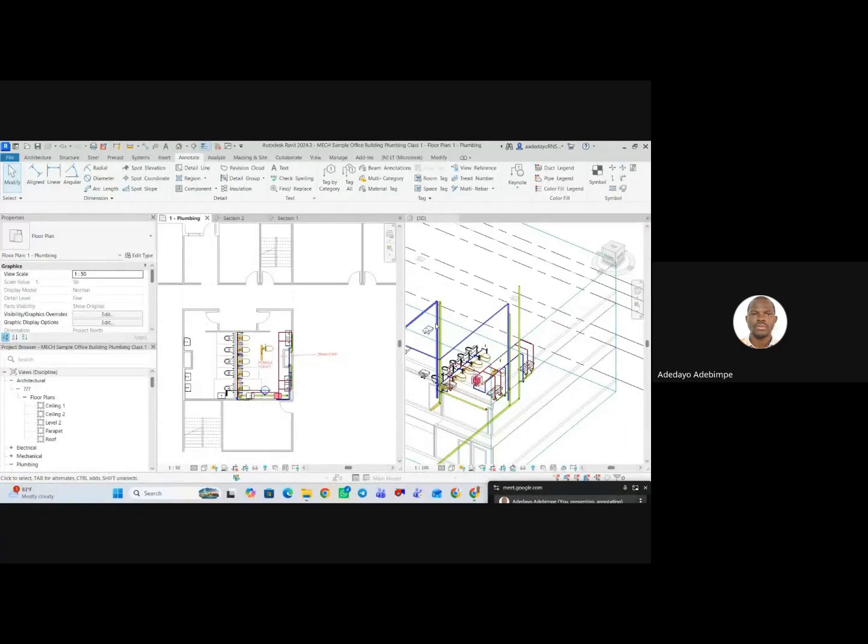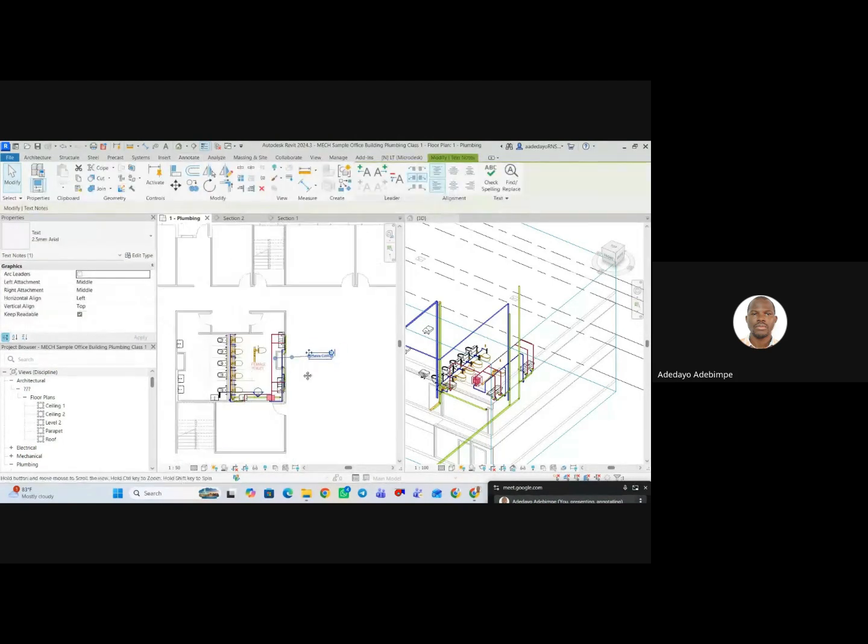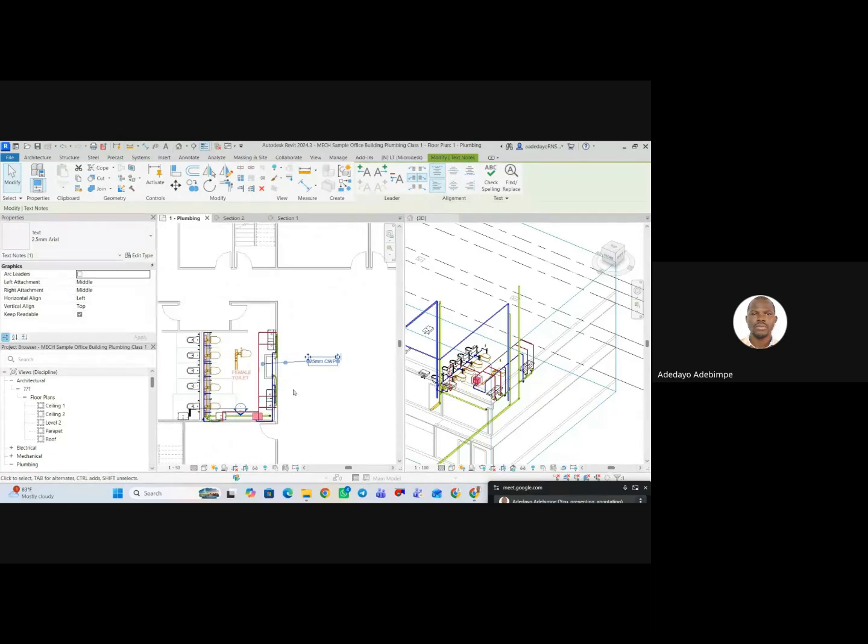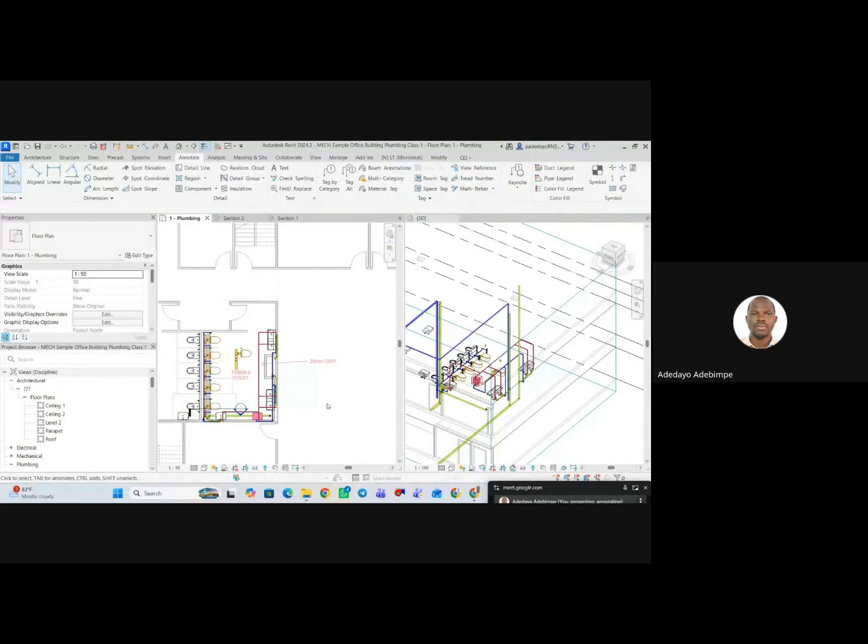Now, for you to know the size of your text, you see that when I go smaller in scale, my text also goes smaller. So I will say 50 times either my length or breadth, I need a constant reference, maybe the breadth of my sheet. 50 times 450. That will tell you around the size your text will be.